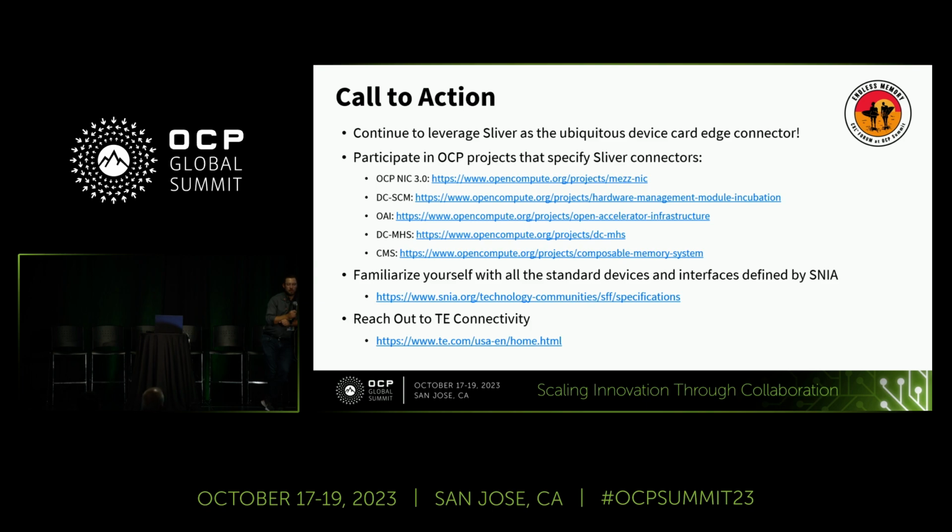Yeah, and the other thing here, maybe connectorizing the card edge. So instead of going to a Goldfinger edge, putting some sort of connector on the device itself. So you pay the penalty on the device, but you get, like you're saying, use the Z height to get up. Right. And we also shared with the team this morning and yesterday, we need a copper backbone. We need a number of these things to be linked together out of one assembly.